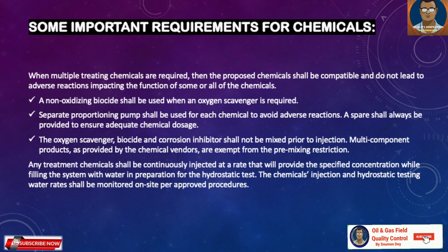restriction. Any treatment chemicals shall be continuously injected at a rate that will provide the specified concentration while filling the system with water in preparation for the hydrostatic test. The chemical injection and hydrostatic testing water rates shall be monitored on site as per approved procedure.